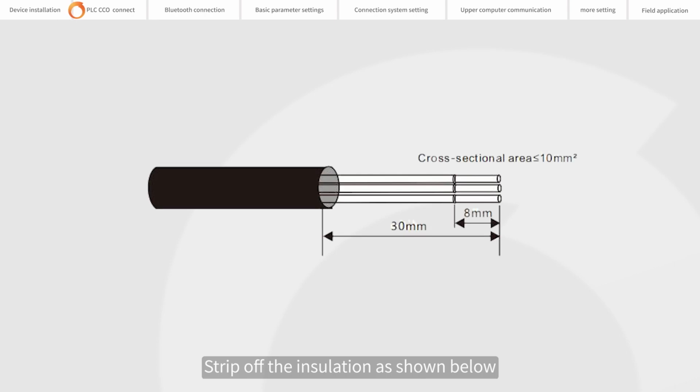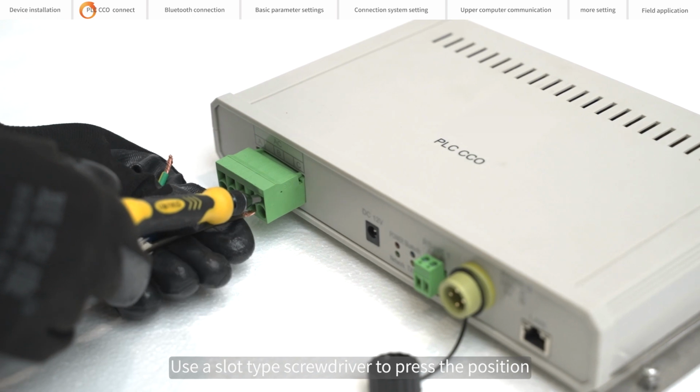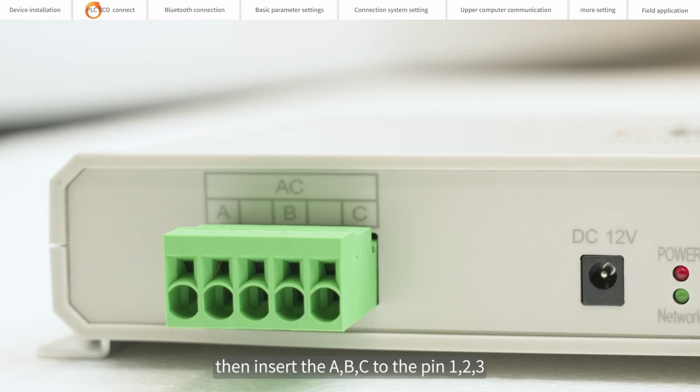Strip off the insulation as shown below. Use a slot-type screwdriver to press the position. Then insert the A, B, C to the pin 1, 2, 3.